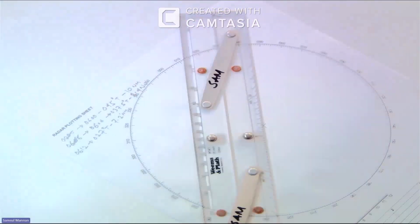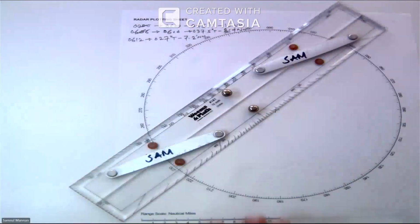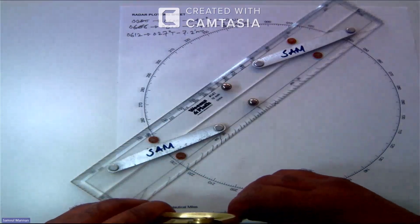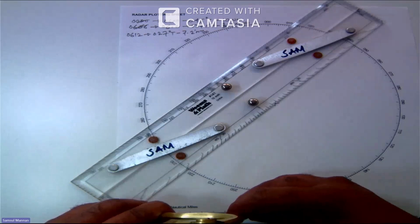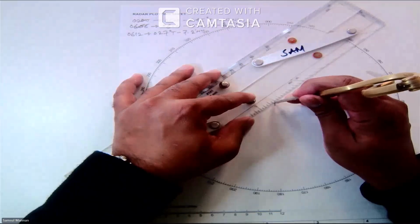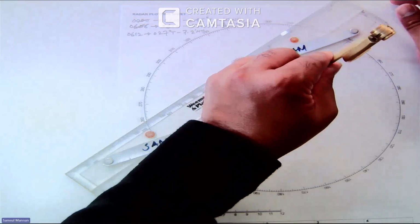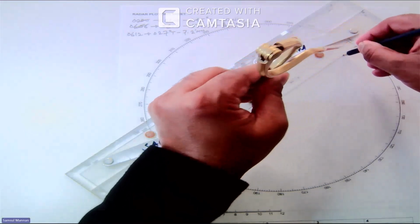So you see, I have kept my parallel ruler at 045 degrees true, and I have taken a divider, and I'm measuring 10 nautical miles in the radar plotting sheet, and I have put my first range and bearing in the radar plotting sheet, and I have marked that one.